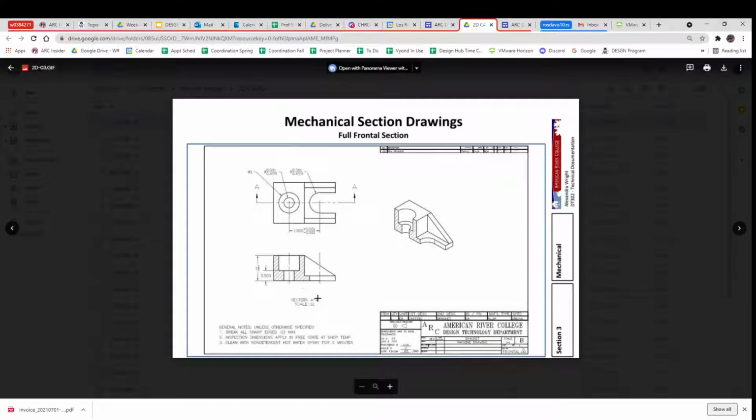What makes this a good professional style drawing? There's good line weights. These are all in good positions. There's standard tolerances. It tells you how much it's made from. It gives you a nice visual. This is a little sloppy right here, but it's still pretty professional. These are all coming off between 15 and 75 degrees. That's an important thing. Special tolerances are on there. There's notes.